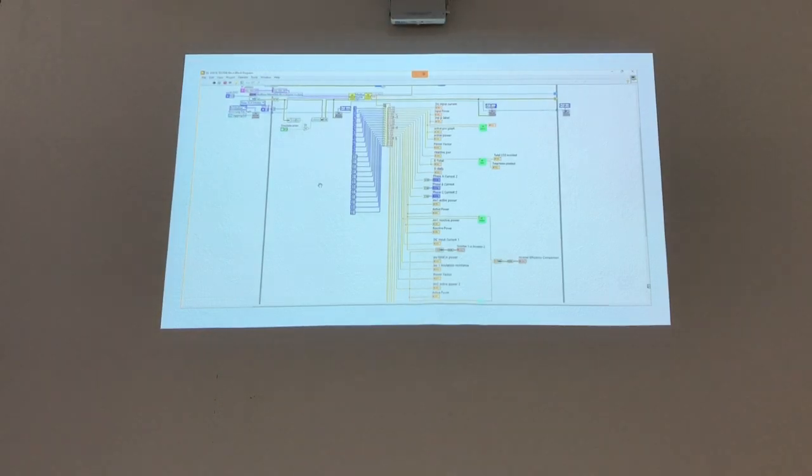So you know the impact: if the further down system is almost as efficient as your inverter, say both are 97, that's good news. But if both are also 90, then it's bad news. Overall, the whole system is only 81% efficient. That's why you want to keep the efficiency high, because further down the system may not be so good. You lose energy.